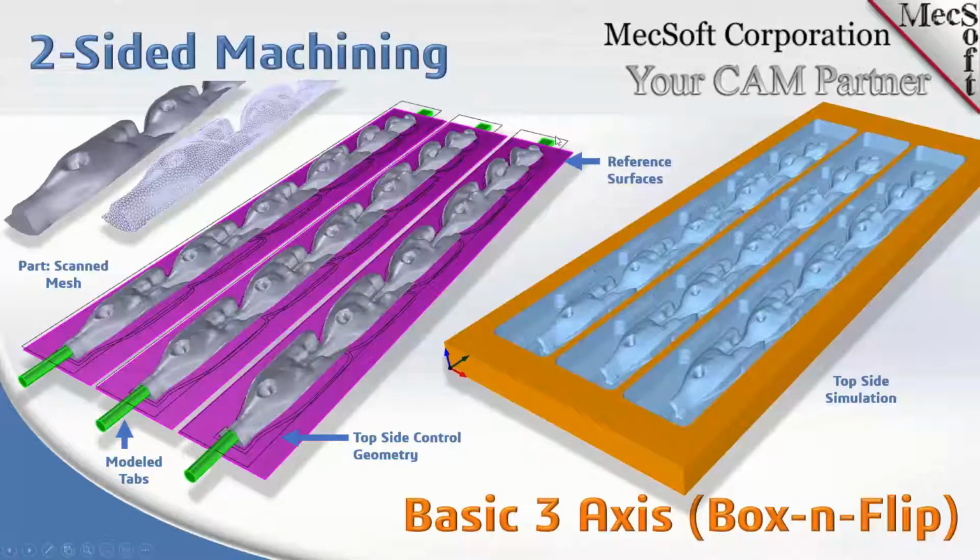On the other end, we don't have a lot of room for a cylinder rod, so we modeled just a square block that comes in underneath the part on the end. And like I said, it doesn't have to be a cylinder. It can be any type of surface that's going to break up the toolpath on each end so that it remains connected to the stock material.